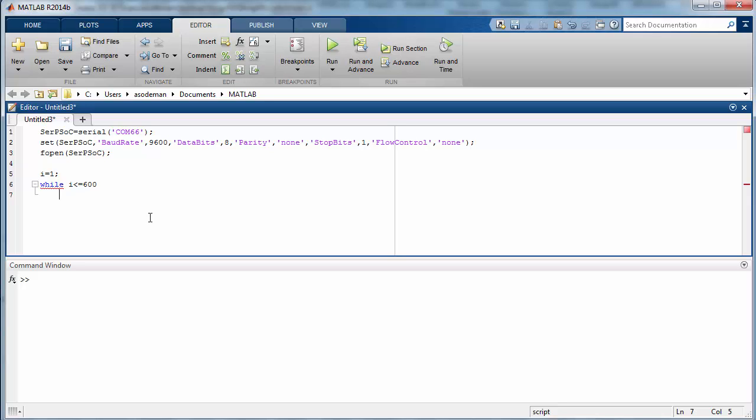We're doing this on purpose because if we would, say, lose 1 byte between the PSOC and MATLAB, we still want the MATLAB code to finish successfully. And if we would be off by even 1 byte, MATLAB would sit and wait for a byte to come until it times out, and we would get an error.